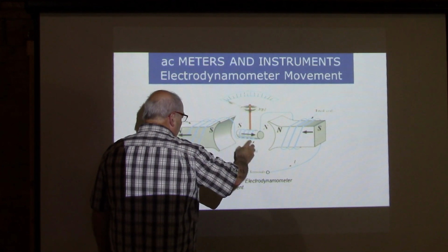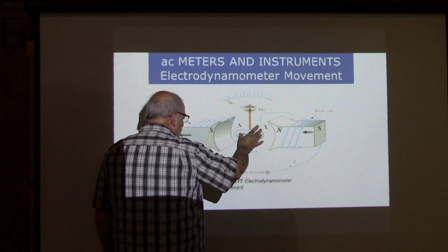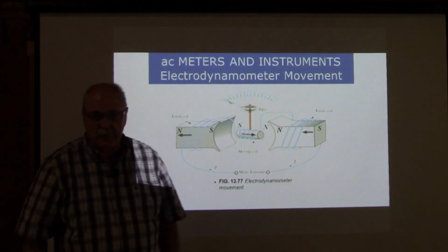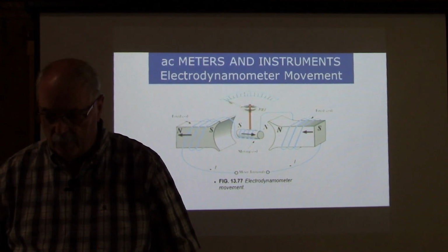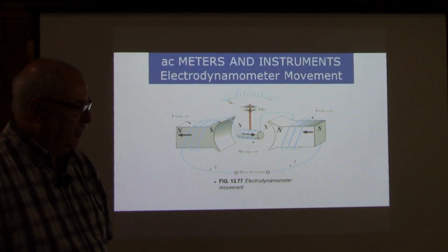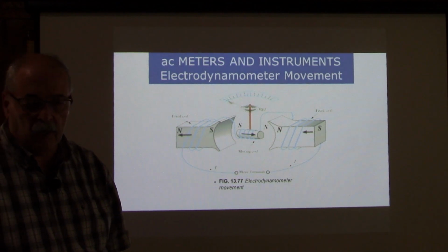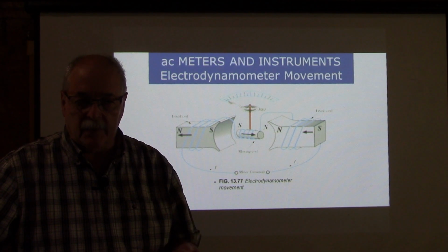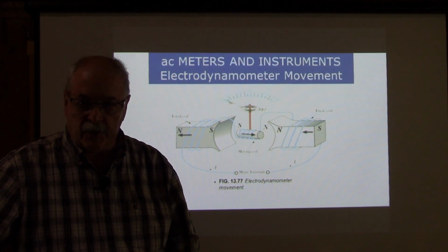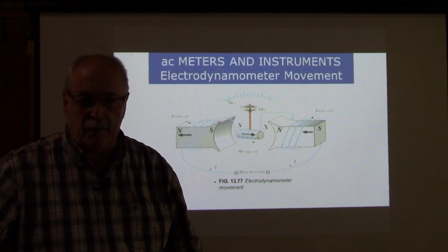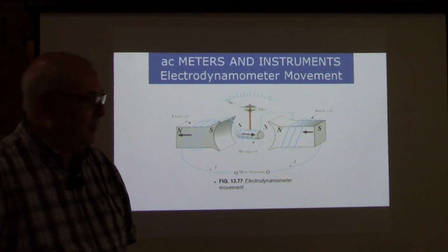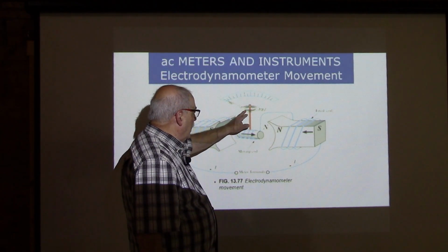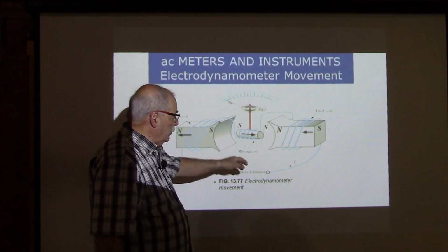If you think about this, it looks very simple, but it has to be able to pivot, and you see these wires connected. There's something called a D'Arsonval meter, and it's amazing. Years ago, you paid a lot of money for these because they actually used diamonds to pivot on. You did not want friction. Friction was your enemy; if you had friction, you couldn't get an accurate number. And these little coil springs also acted as a feed for the voltage into the magnet.